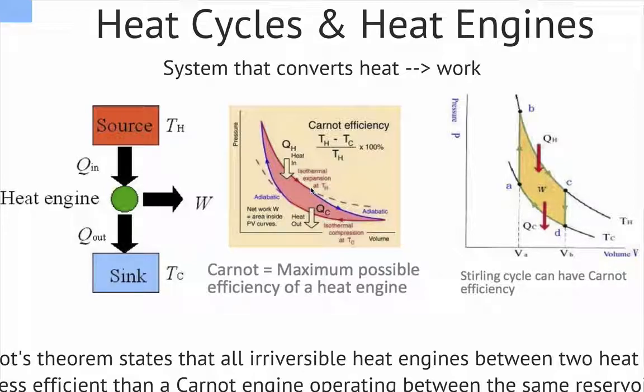And then there's something called an adiabatic expansion, where the temperature can change. In this case, the temperature falls, going from TH to TC. It's also undergoing an expansion, but in this case it's also expanding and reducing in pressure. So at this point of the cycle, you have the fluid at very large volume, but low pressure, so it's existing as a gas.